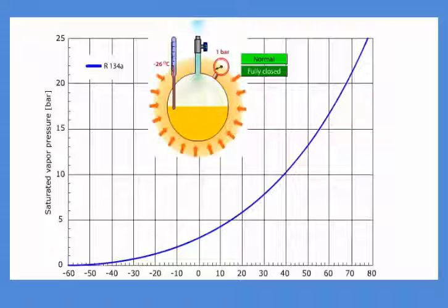You can see that the saturation pressure depends on the temperature of the mixture. The higher the temperature, the higher the saturation pressure. The saturation pressure is a unique property of the substance. The different refrigerants do not have the same saturation pressure-temperature dependency.